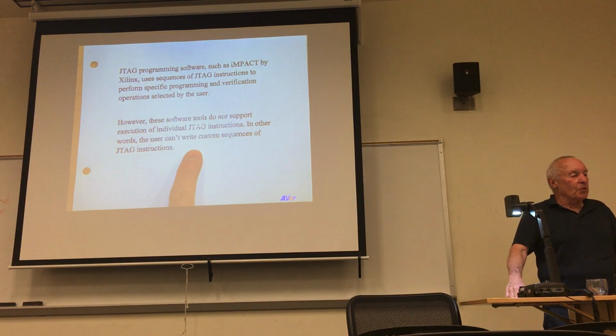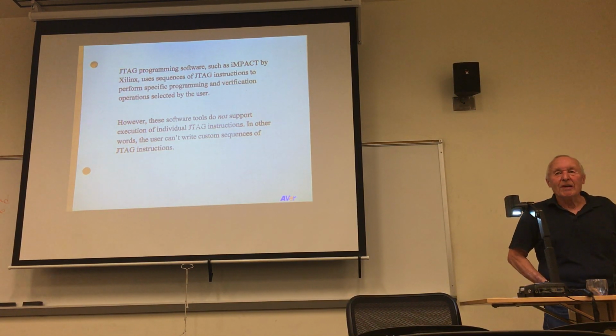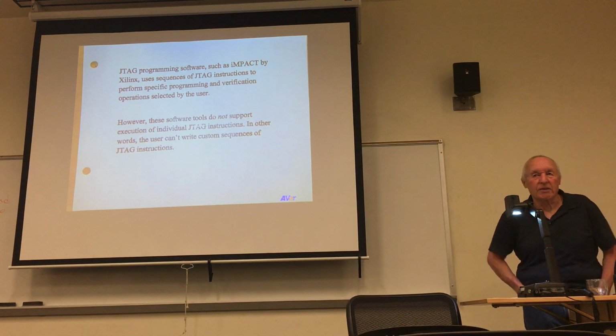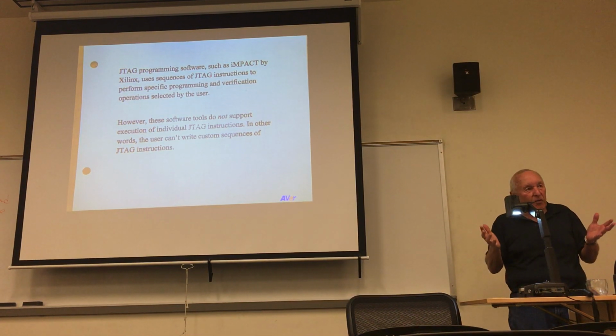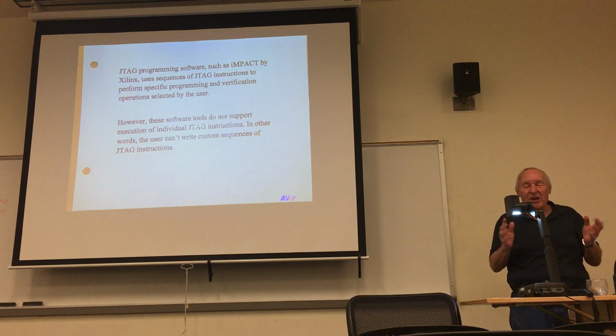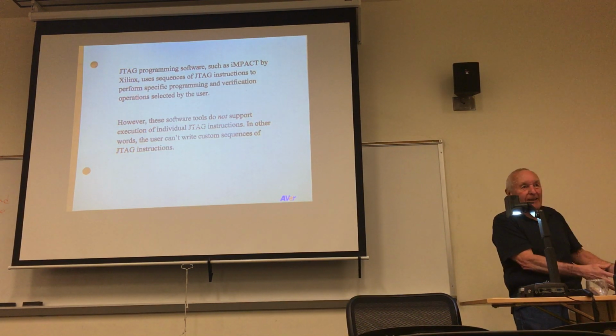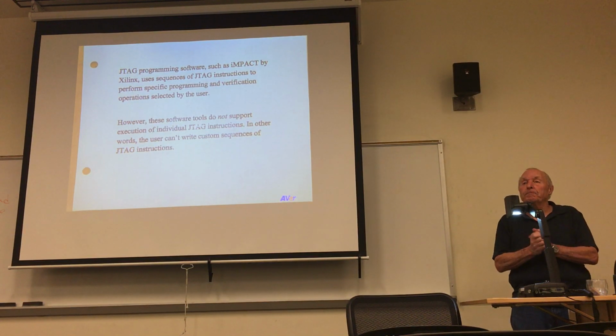These software tools do not support individual JTAG instructions. In other words, you can't write your own sequence of JTAG instructions to do something and expect to use the iMPACT software to do that. The JTAG driver software in iMPACT is designed for one and only one purpose, and that's to do those 19 steps to program an FPGA.